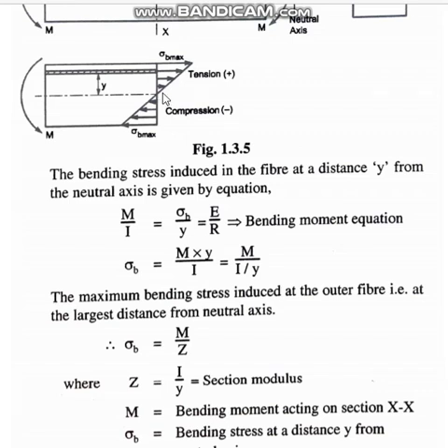So now what is bending stress? Is it tensile stress or compressive stress? Bending stress can be either of these. Actually, bending stress is a direct stress. It is either tension or compression, because some fibers will be experiencing tension, some other fibers will be experiencing compression. So the extreme fiber will have the maximum bending stress, and the fibers towards the neutral axis will be experiencing lesser bending stress. So that's why on the extreme fiber sigma B max is written, that is bending stress maximum.